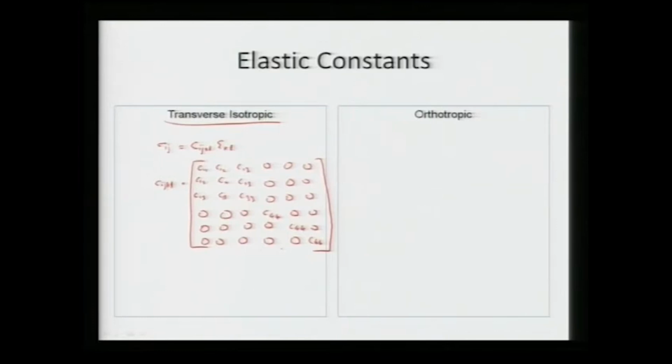So that's how the dependence arises: these particular terms are nothing but the same. So C23 and C13 become the same. The response of the stress in the third direction gives the same result either in 1 or 2. So we can see that particular part arising out here.